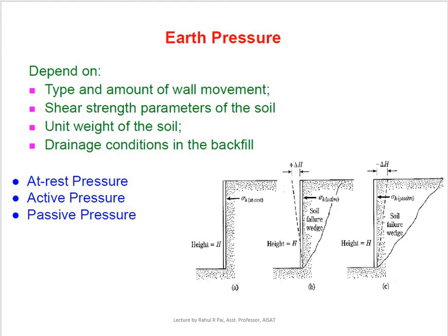It will definitely depend on the strength parameter, that is shear strength of the soil, the unit weight of the soil. That means if you keep on going down, you can see that there will be change in the properties of soil, and this is slightly higher level. If you go to the more deeper level, you will understand that soil properties will change with depth. So that is another thing, and also unit weight of soil. And then comes the drainage condition. Definitely if you go after some depth, there are groundwater conditions. So based on that also, what kind of drainage condition is provided for a particular backfill, that is also affecting the earth pressure.